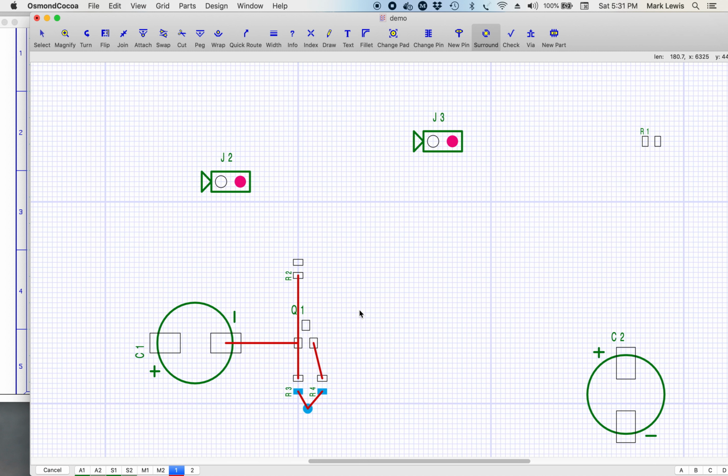That's where our negative of our power, or one side of, let's say, the output. If it's going directly to a speaker, since this was an amplifier circuit, one side would be going there. These are some signals that are coming in. I generally would turn it like this, pin 1 towards the top a lot of times. On my circuit diagram, I make a little arrow that points to pin 1.